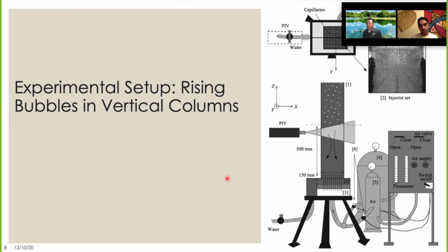I will say one more thing. It's extraordinarily important, especially in two-phase flows, to understand the method of instrumentation with which the data was collected, because it's really easy to generate basically superfluous data. Data doesn't provide good information. So if you just look at the conclusions without critically analyzing the way that they generated their information, that can really lead you astray. For the type of bubble-generated turbulence you're talking about, a lot of work has been done on that, especially utilizing really high-fidelity experiments with local probe measurements and things like that. So it's really important to fundamentally understand the way that you're generating your data for the model development and for your analysis. Yeah, I follow what you're saying.